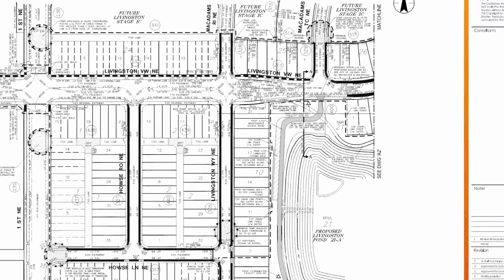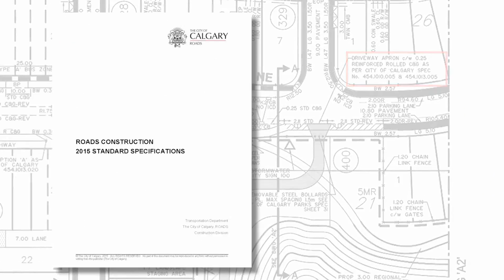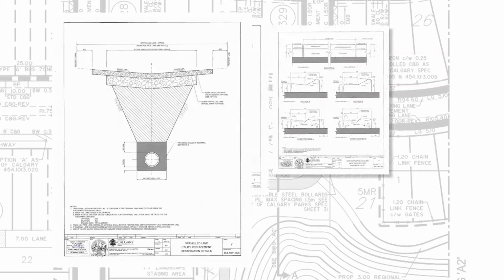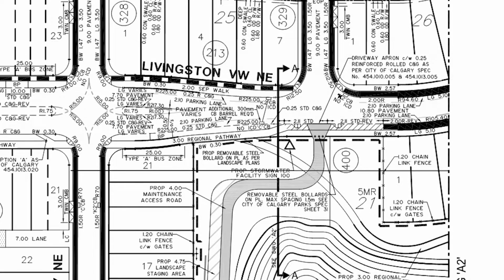Another type of note refers to specifications. Specifications are standardized drawings for common structures found on jobs. These include different types of curb, pipes, roads, lanes, walkways, etc. You can find specifications in the spec book for whatever municipality governs at the applicable job site.